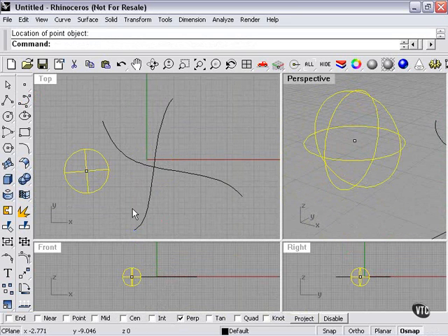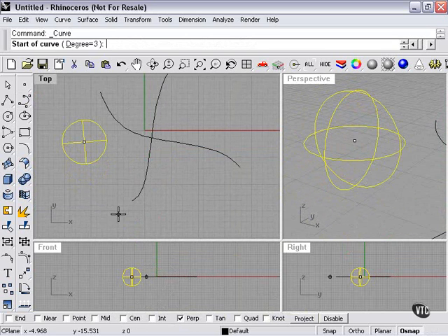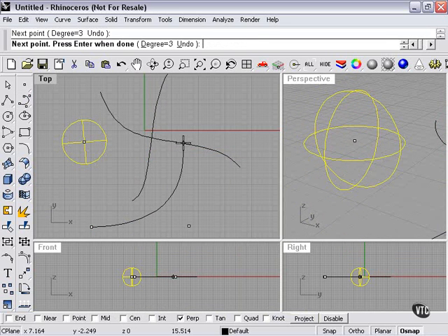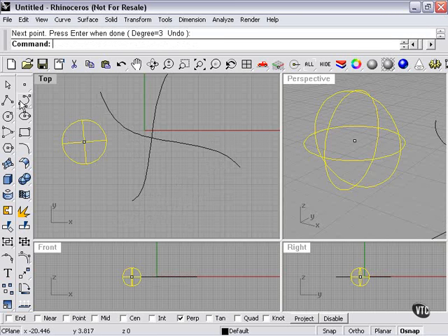Perpendicular object snap is kind of interesting. What that does is allows me to create, for example, if I create a line, it will only snap to a point that is exactly perpendicular. And on some curved shapes, it may be difficult to actually find someplace. For a guarantee, let's create two straight lines. For that, I'll turn on my regular snap. So I'm snapping along my grid here.